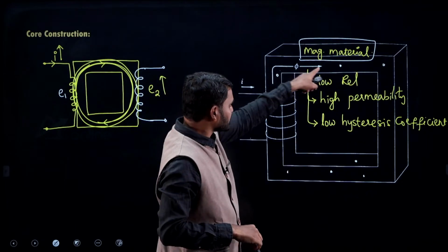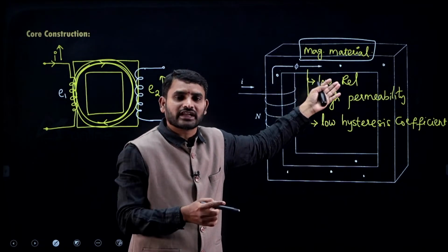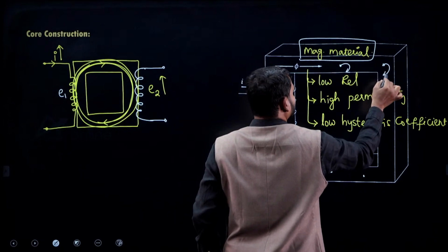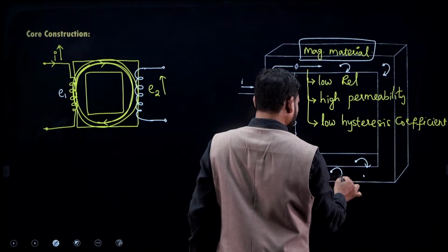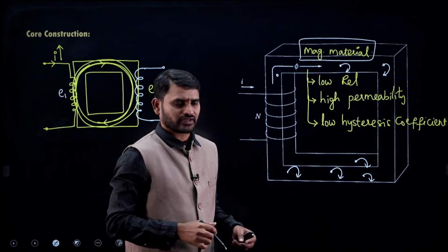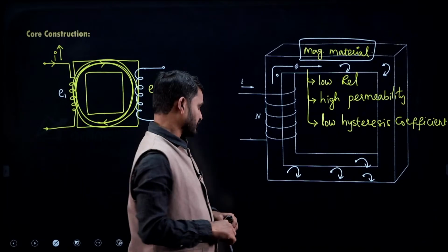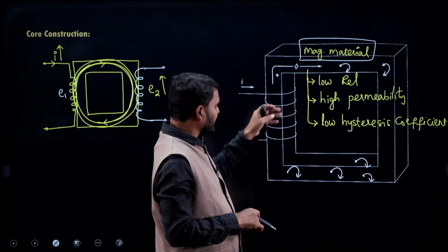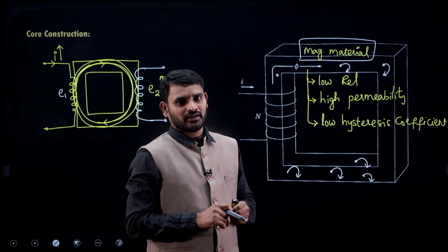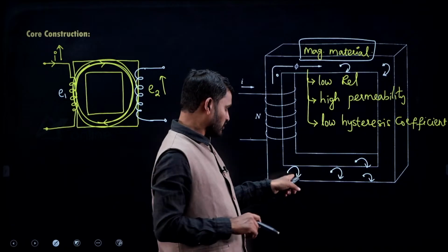So, when an alternating flux is establishing through the core, those flux lines will definitely interact and create some force on these free electrons. That force we call EMF. EMF is nothing but what? Electromotive force. A force is created on the electron because of these flux linkages, right. This EMF is not induced in the winding, it is induced in the core. It is useless actually, we do not want that. In the core, only flux establishment should be there, no? EMF should not be induced.